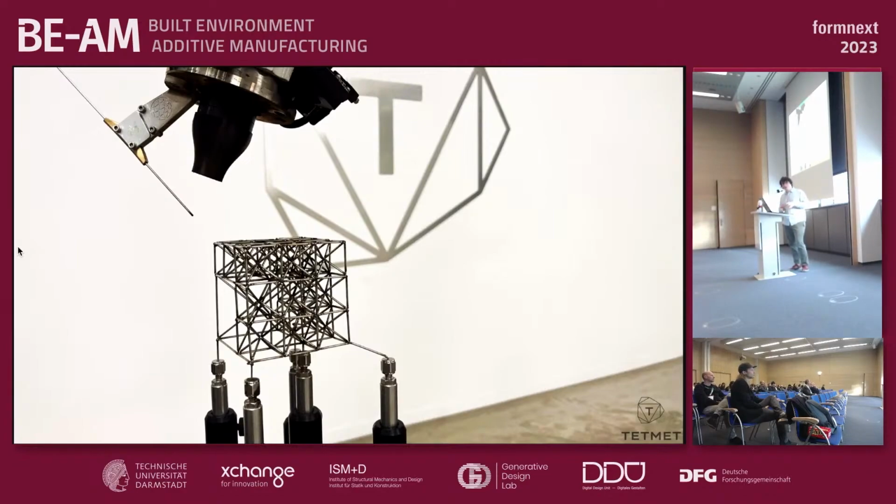The thing is, right now the parts we are working on are structural components that need to be very stiff. If to start with you have bending in your struts, it will be less stiff than a straight bar, just because bending stiffness is lower than compressive stiffness.